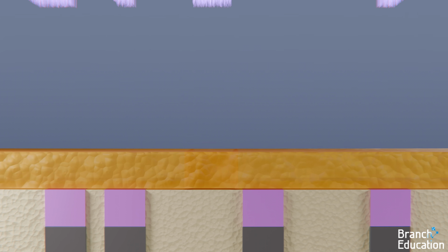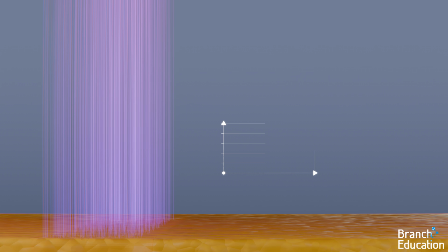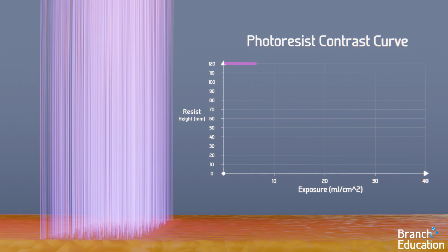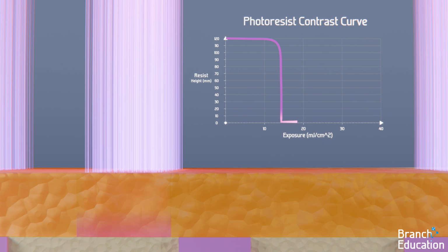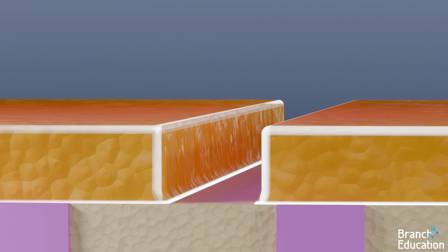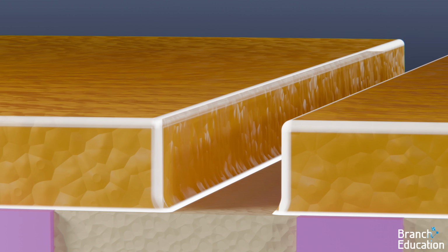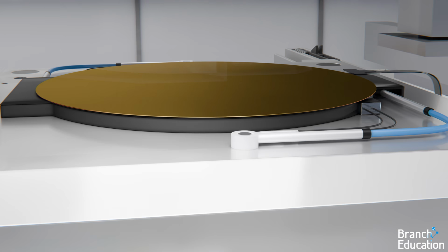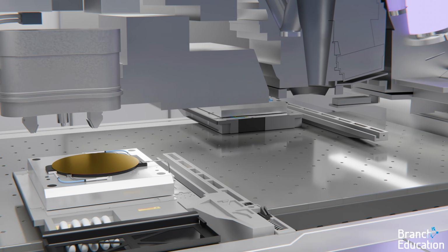One detail is that the resist has an extremely high contrast, meaning that at a certain level of EUV light, the entirety of the resist hit by that light is broken down. This is critical in producing sharp patterns and walls on the resist. Let's next explore how the wafer and wafer stage move around.